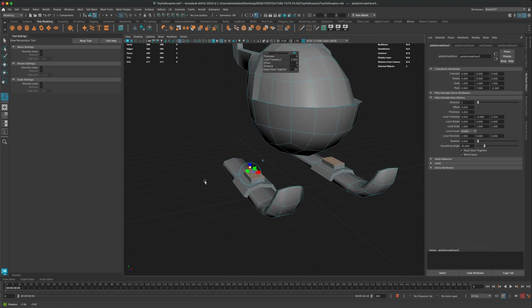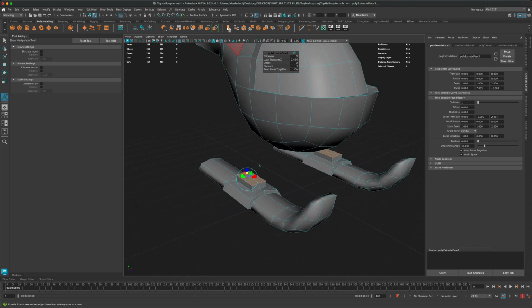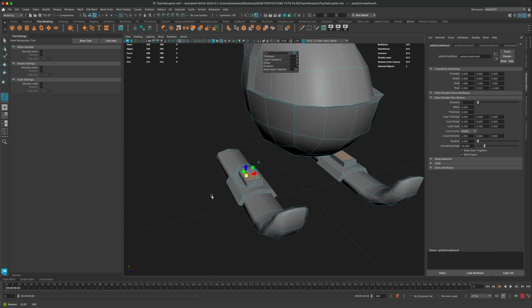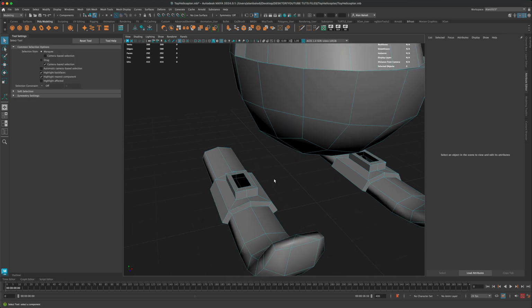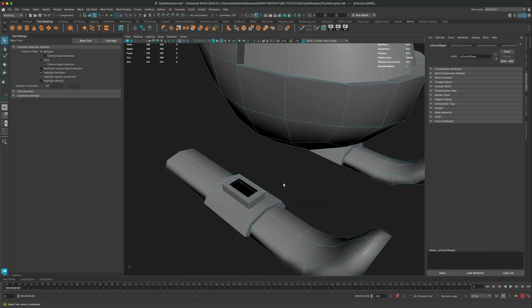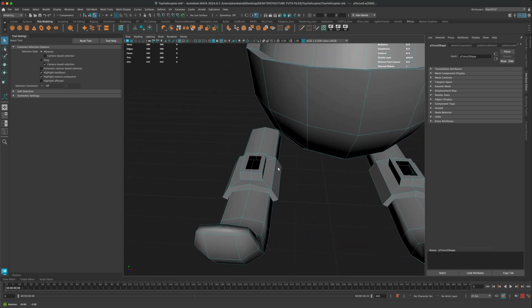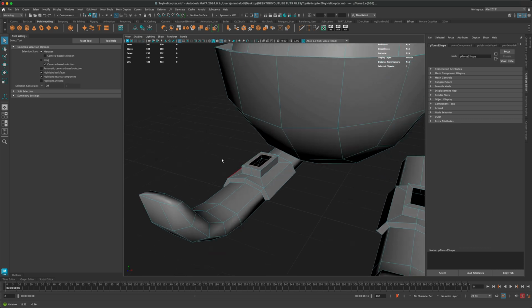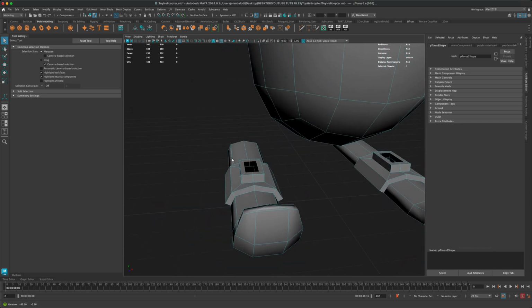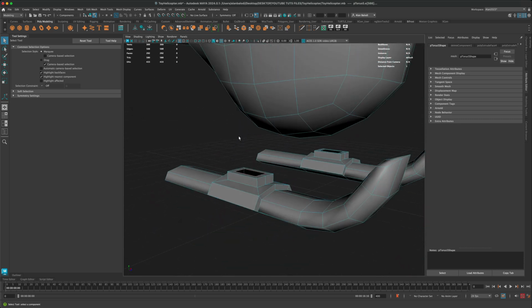I think that's very nice. Let's do extrude again. Click on the outside of the box and pull these in. Maybe pull this in. And next I need to delete these faces, so I'm going to press delete. All right. Now, one thing I need to be aware of is the number of edges that is on each side, right? In order for me to make a bridge.